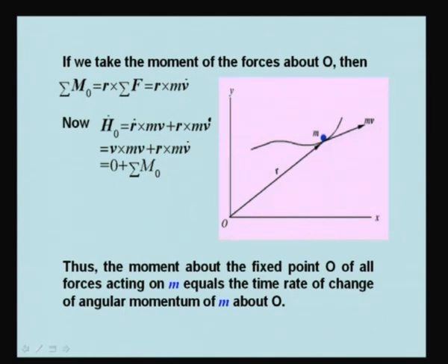We have derived it like this: h dot o is equal to r cross m v dot, and if we have a system moving with a constant velocity, then its effect is not experienced. It means that if it is valid for mv dot, it is also valid for m(v plus c) dot, and therefore this relation holds good for point O which is moving with a constant velocity.